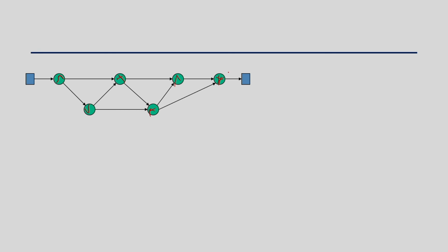These are the gates, and how is the clock period determined? The clock period is determined by the maximum combinational path length. That means it is the path between two sequential elements, or the path from input to some sequential element, or the path from a sequential element to the outputs. Basically the path consists of only combinational units, so there is no sequential element involved in a combinational path.